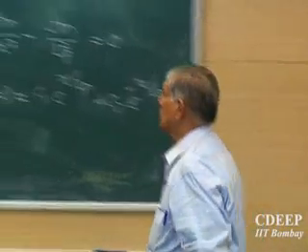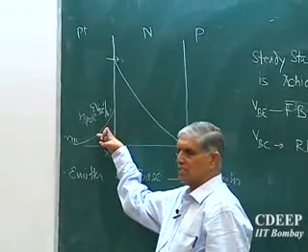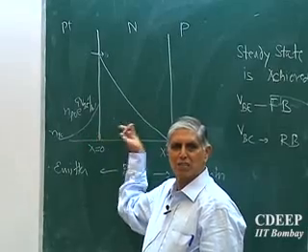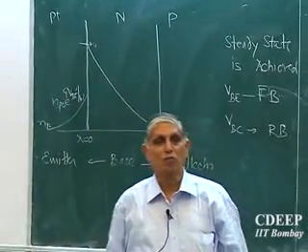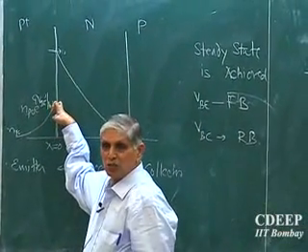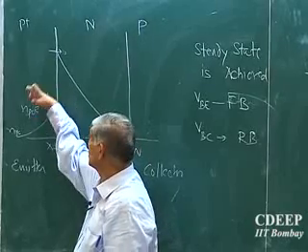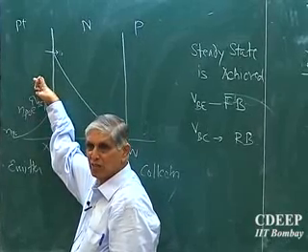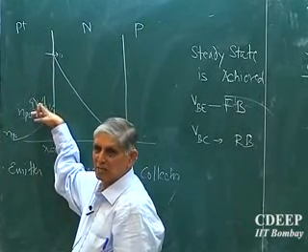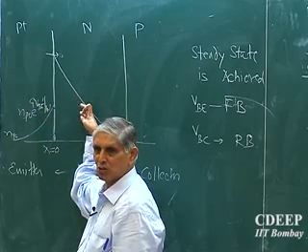Right now, I may say there are other currents also possible. This current, which we may right now neglect. We may say all that emitter current is given by the whole current. What is this condition telling? If this value is extremely small, that is, the doping in the emitter is very, very heavy, the diffusion current coming from here, q dn by dx, will be extremely small compared to q dp by dx on this side.